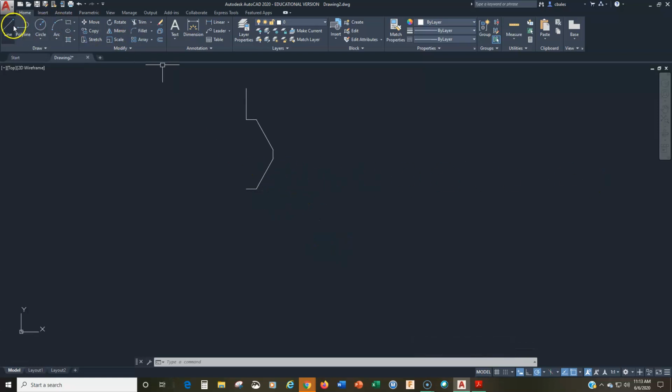So now we want to rejoin. We want to grab hold of this end. So of course we want to use object snap. Please, please, please, you got to use object snap. We want to draw down some distance. How far do we want to go? Can't really tell. We don't really know here how far we have to go. Now, yeah, we could do some math to figure that out.